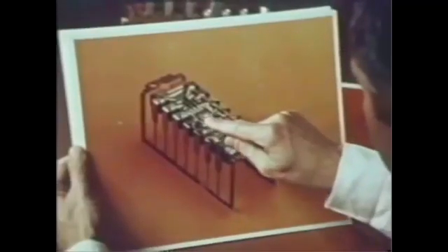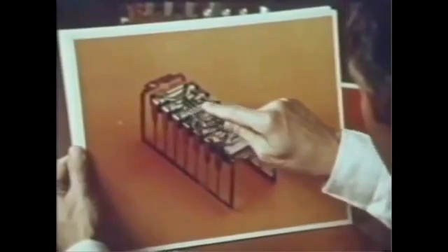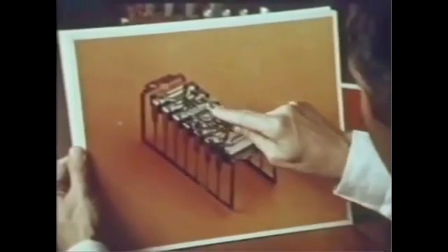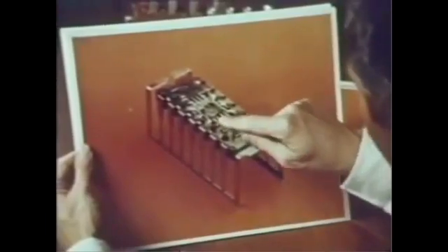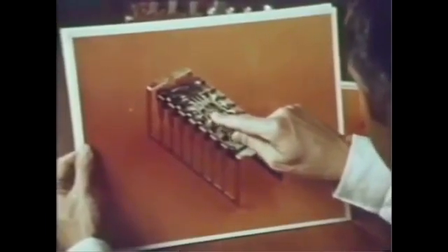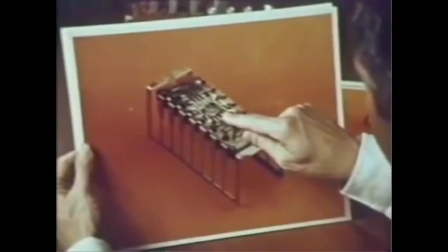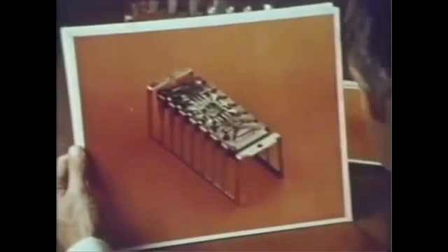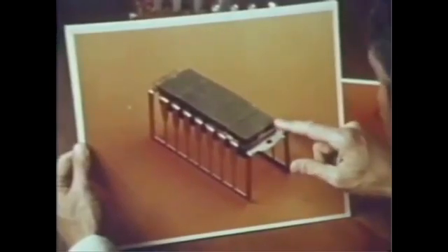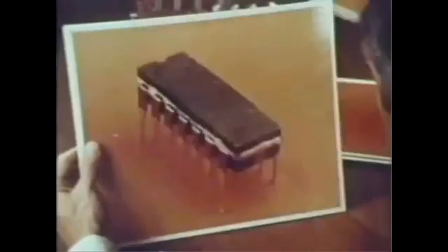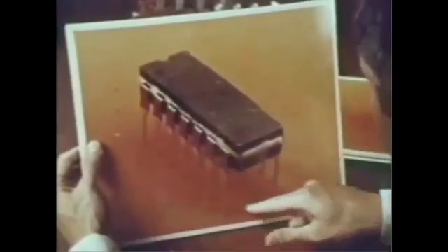And here is the arrangement. Chip in center, Kovar frame around the outside, and notice that the tips of the frame here have been metallized. This will form the connection to the chip directly, as shown here, where the lead bond wires have been placed connecting the pads on the chip to the metallized tips of the Kovar frame. We complete the sandwich by putting the top half of the package right on top of the frame. The next operation will be to clip the ends of the frame. The package is now revealed in its magnificent beauty.